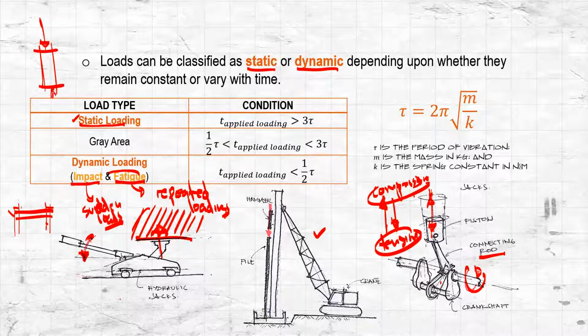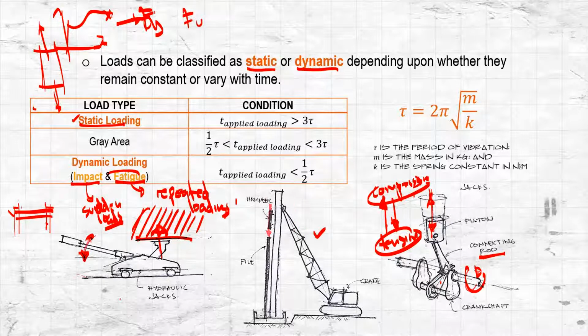So we have learned already that when you subject this steel in compression, or let's say tension. Okay, once we subject this steel specimen in tension, we already know this stress strain diagram. In this stress strain diagram we have obtained the yield strength, right? The yield strength, or the Fy, and also the ultimate strength. However, when this specimen is subjected to fatigue loadings, the strength would be much lower.